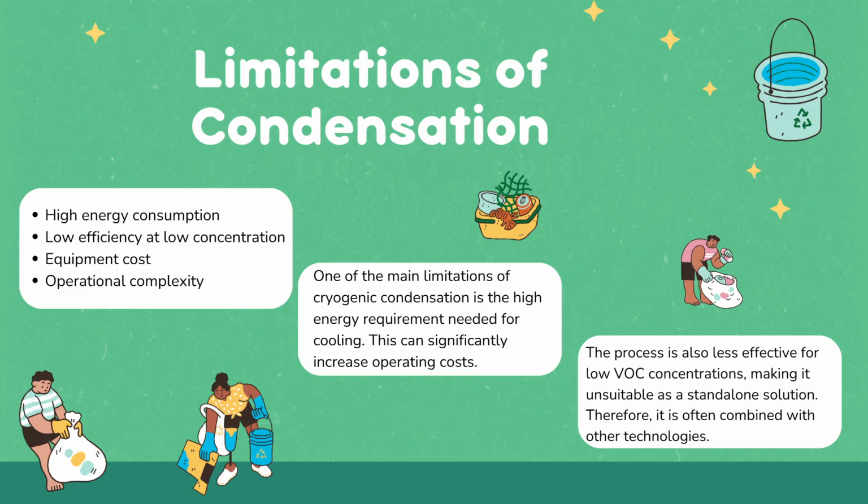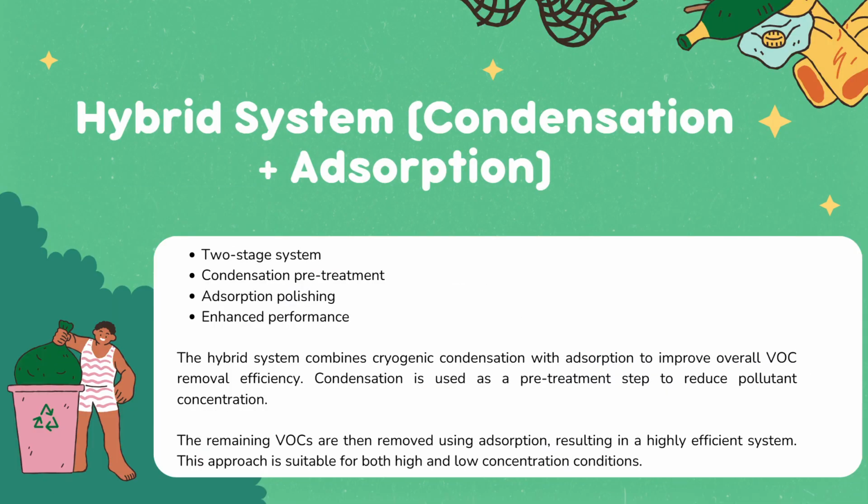One of the main limitations of the cryogenic condensation is the high energy requirement needed for the cooling. This can significantly increase the operation cost. The process is also less effective for low VOC concentration, making it unsuitable as a standalone solution. Therefore, it is often combined with other technology.